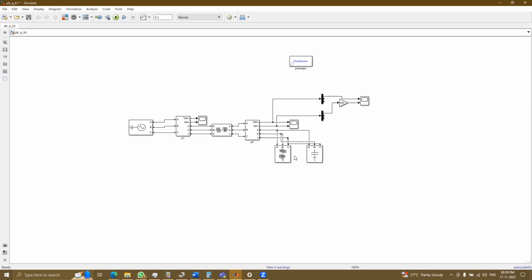That is a calculation. If you do it by hand, you need to calculate the impedance and then recalculate accordingly. There is a formula, Q equal to P tan phi, and you need to put that phi value in the tan. Then you need to get the P value. Accordingly, you will be calculating Q. So P is already known, 100 K. Q is unknown or negative.